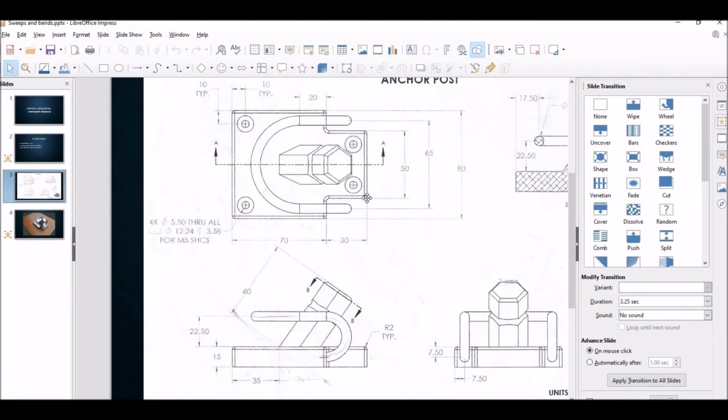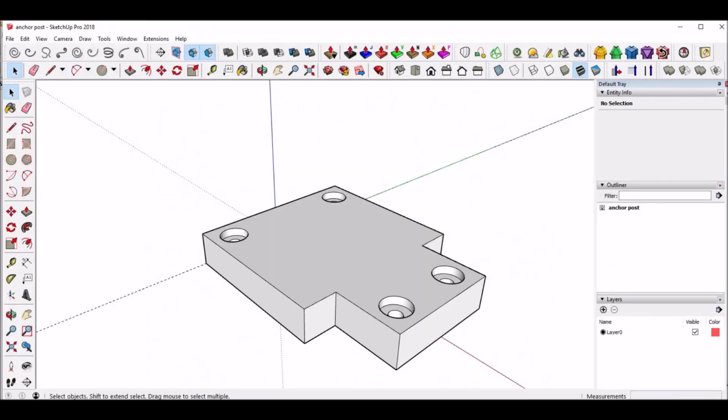Okay, this radius, these rounded edges, does it show what that is? Yep, 2 millimeter rounded edge. So I will show how to round those at the very end. I'm going to be using an extension called Fredo Corner that's going to round all of these.